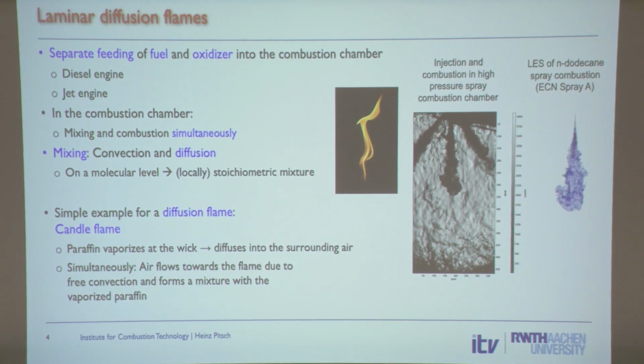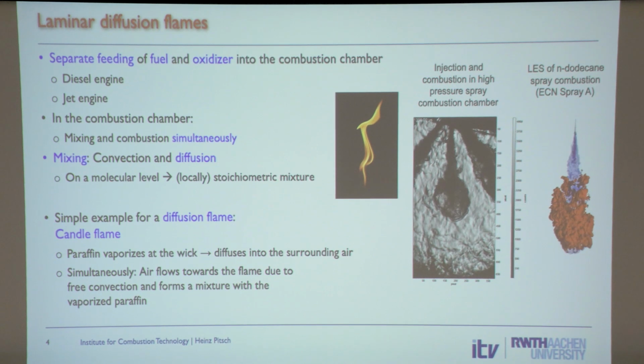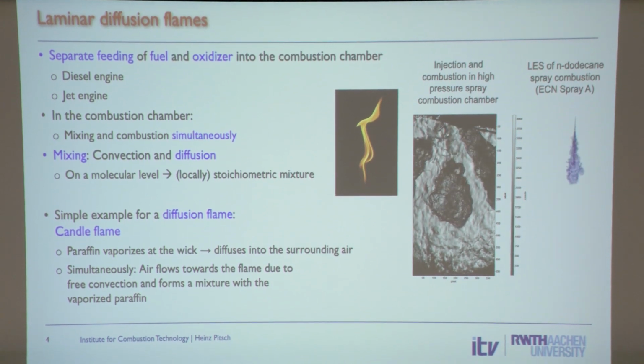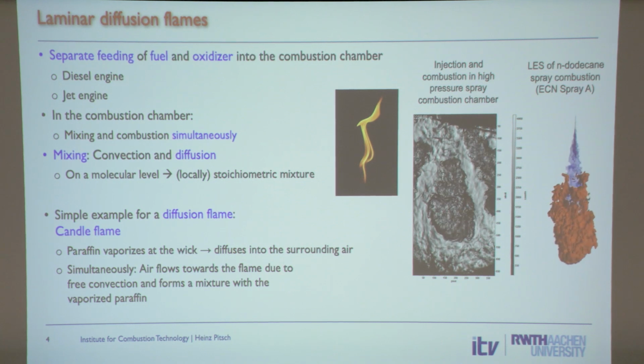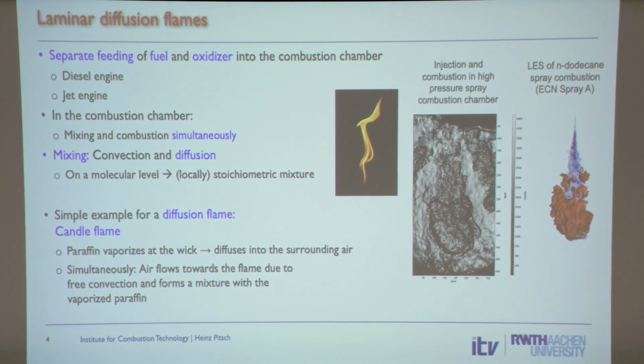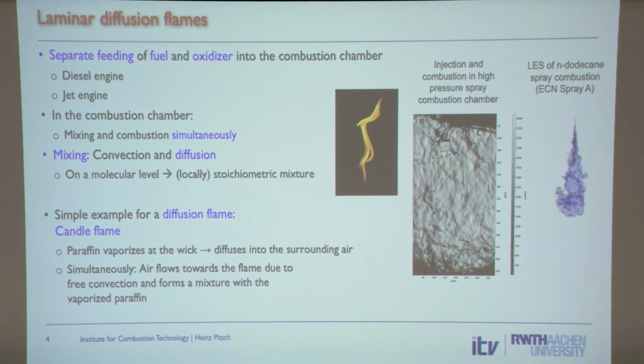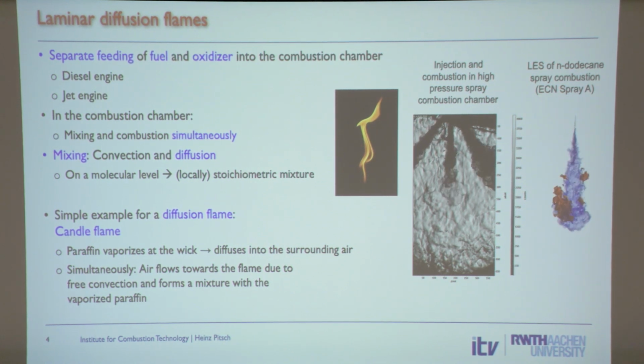Why constant pressure? Because you inject, and then it mixes a little bit. After it ignites, there's a lot of partially premixed mixture that burns premixed all at once. That's the constant volume part. But after that, you still have rich regions and lean regions, and combustion only happens because of mixing.